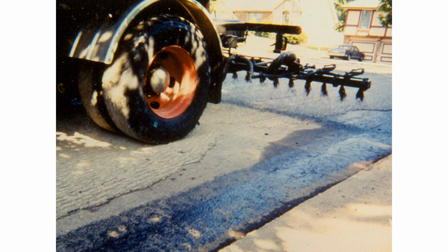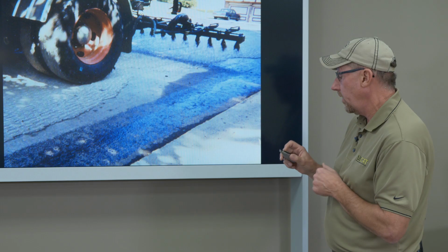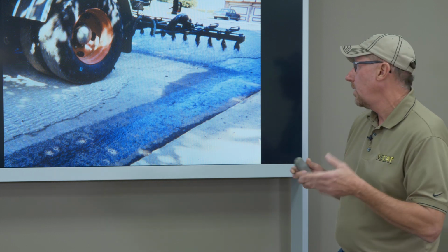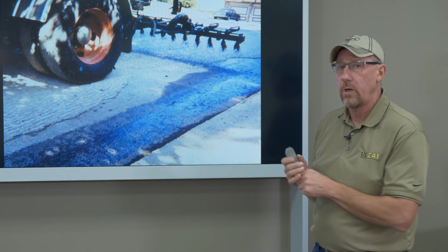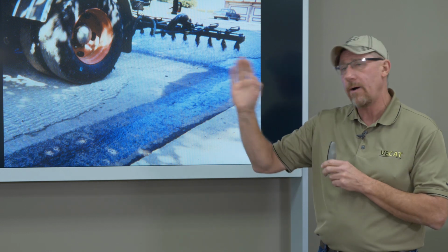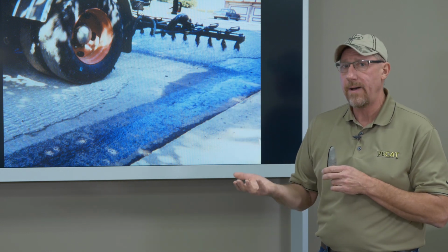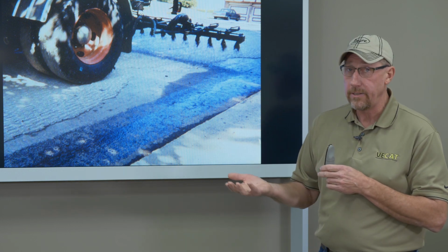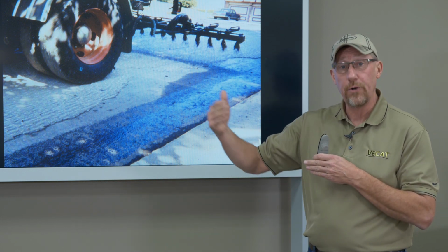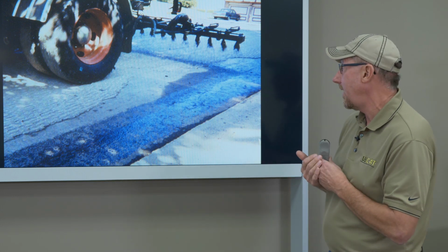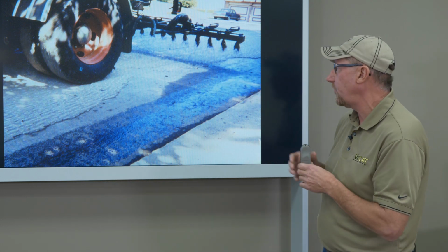Another example of it, I back along the curb so I'm not getting any up here on my sidewalk, give myself a little playroom, 1 nozzle per foot, my bar's up a little bit, I can then take off and get that uniform coverage all the way across and not have to go very fast to do that. It's inherent that on mainline paving, we could set everything up that will work well at a slow speed, but as soon as an operator sees a lot of road in front of him, even though the paver's going about 38 feet a minute, you're not going to catch a distributor truck, but they feel they got to go 20, 30 miles an hour to be able to accomplish what they want. So we want to size them what works best for you.